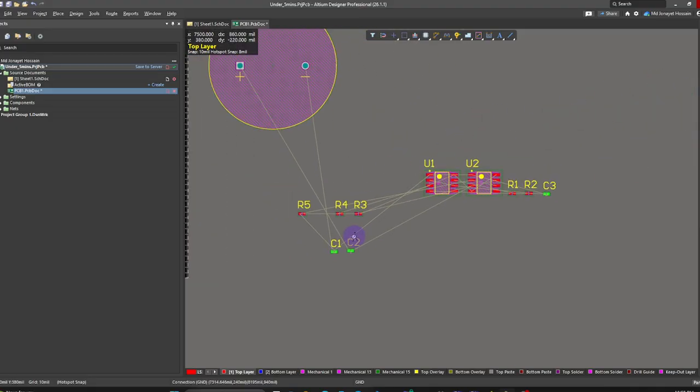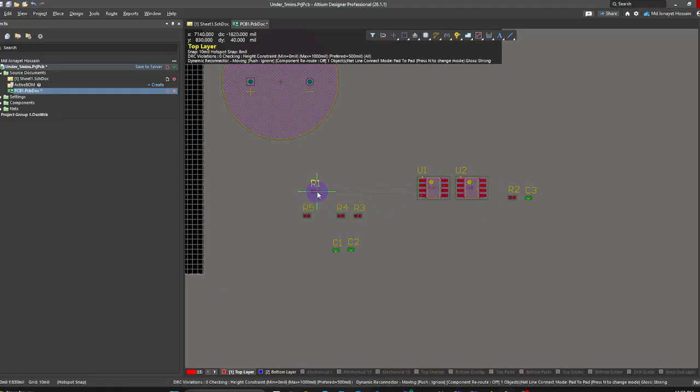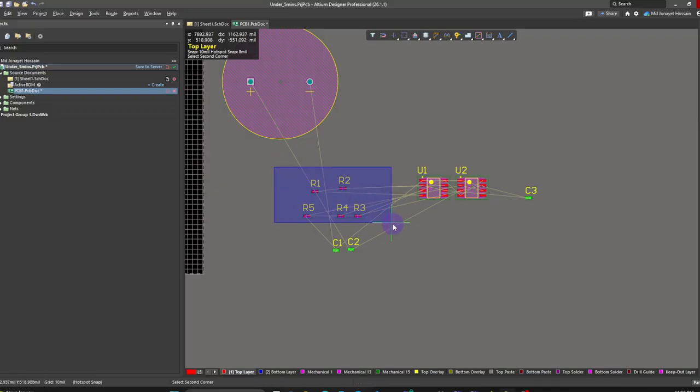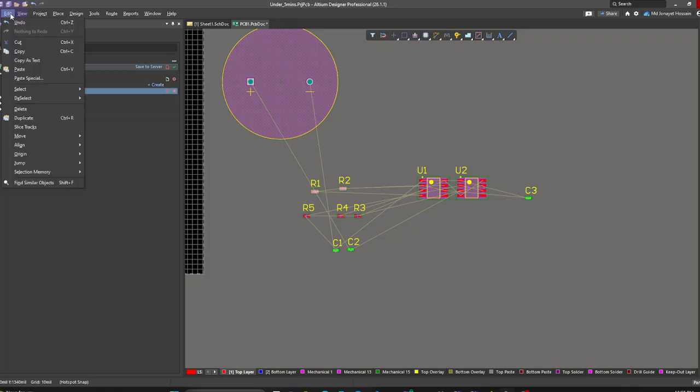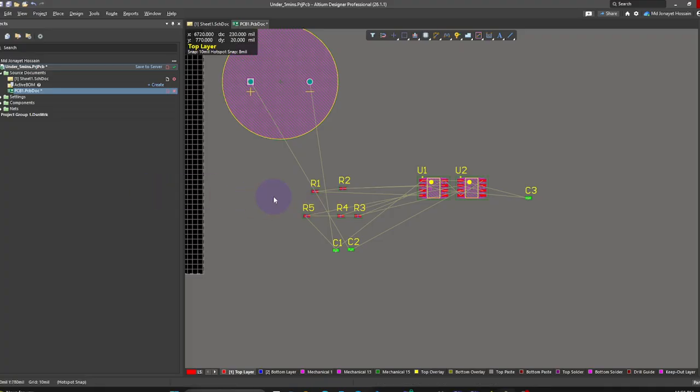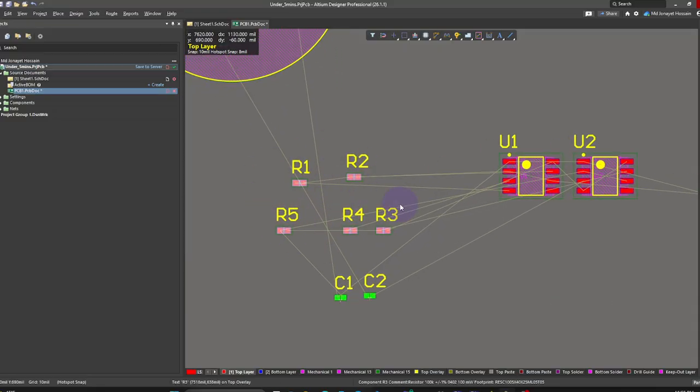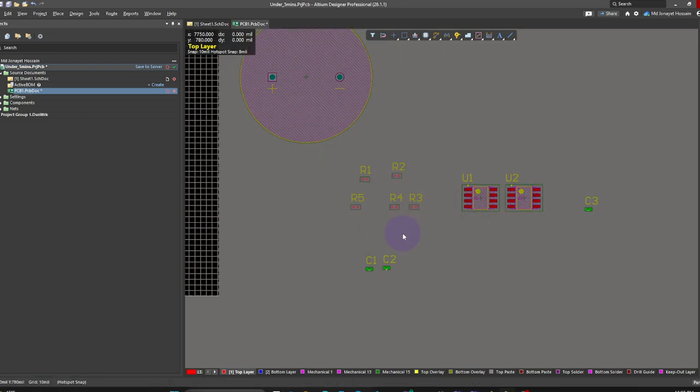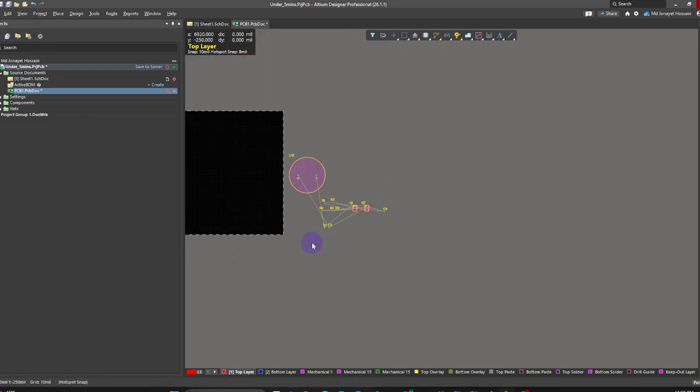But later on, if you decide to add these 2 more registers too, and you want to have them in your memory selection as well, you can select all of them, or maybe just 2 of them, go to your edit, go to memory selection, store plus, and Shift 1. Now if I press Alt Shift 1, I'm essentially selecting all 5 registers, which is pretty cool. It's going to be very handy based on how you use it.